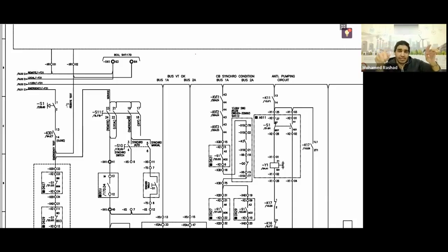So if you have selected the breaker and pressed close, this close is supposed to go and shut off all the equipment, or what is called in Egypt mohimat, if we say it in Arabic, or all the components you have, whether it's the disconnector, earth switch, or circuit breaker, it sends them all a close command, but the circuit is not complete because you haven't pressed your select button. So what you will press is the select button and then press to close. This is the only one responsible for closing.